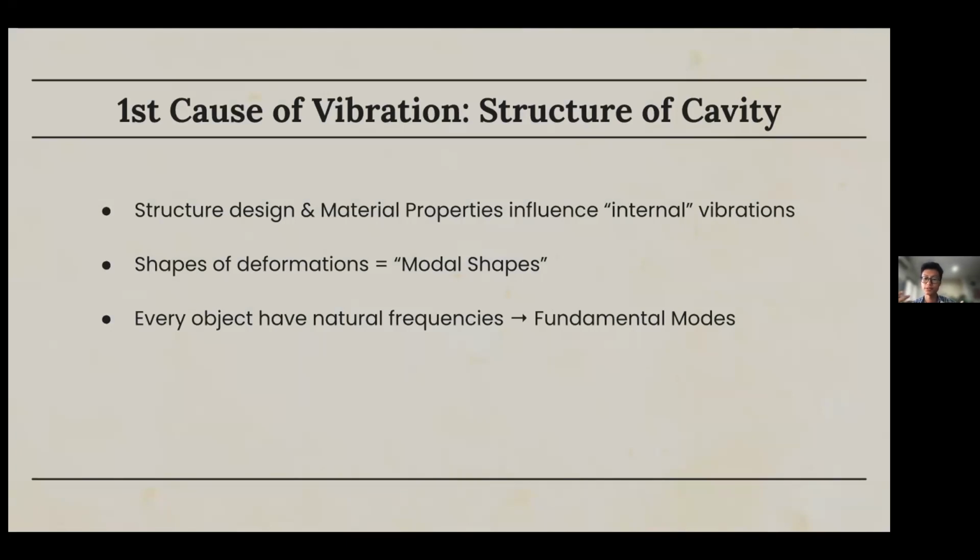Now, when the reference structure induces certain modal frequencies, it displays a variation of deformation in its shape that is also known as modal shapes. However, every object with a specific material composition will oscillate at a particular frequency called a natural frequency. When the natural frequency is excited, the object will undergo deformations that will be considered drastic for an instrument like a reference cavity. So for the case of the study, the length of the cavity will be greatly impacted by the fundamental mode, which is the mode at which the natural frequency is excited.